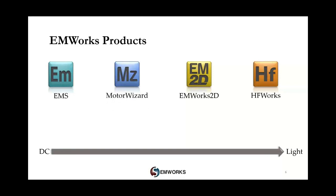Our third product is called EMWorks 2D, which offers static analysis and covers simulation of planar and axisymmetric geometries. And our latest addition in the suite of electromagnetic simulation software is Motor Wizard. This product is a template-based motor design software. It offers analytical and finite element analysis of brushless DC electrical machines. In addition to these solutions, we offer a few multiphysics add-ons like thermal, motion, linear statics, and circuits.